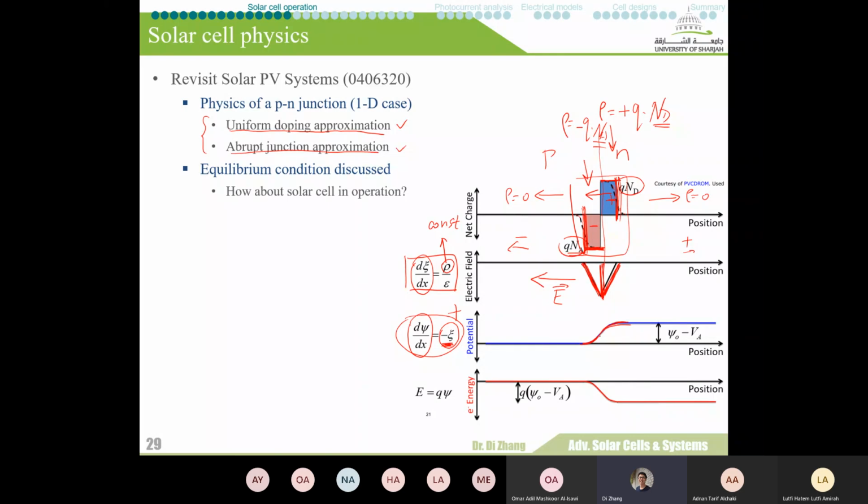And then you can see that the slope of the potential is small starting from here, because the electric field here is relatively small. Then the slope will reach the maximum point specifically at the interface. We have the maximum slope here for the potential, and then after this point, the slope will decrease again, because the electric field is becoming smaller and reducing towards a zero electric field. So that will give us the potential here.